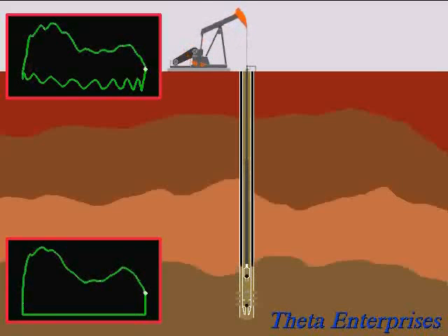that causes the dynamometer card shape to be quite different from a rectangle. And also that wave that we create when the plunger starts to move up will move through the fluid, and when it reaches the surface, it'll bounce off and come back down, and it will give us a reflection on the downhole pump card. That's what this is. This is the original hump at the beginning of the upstroke, and this is the reflection of that as that wave moves up and comes back down.